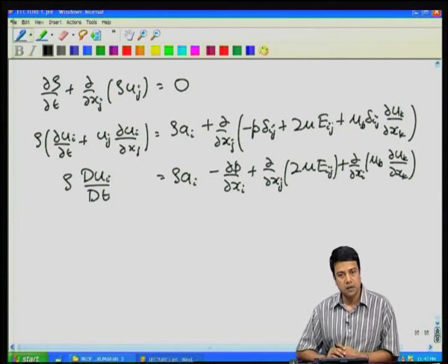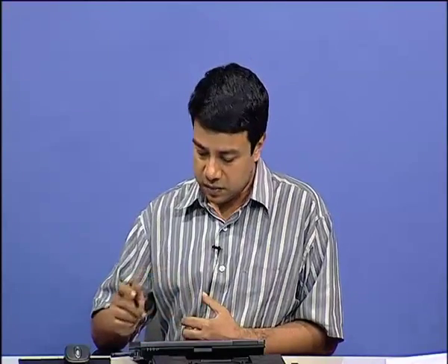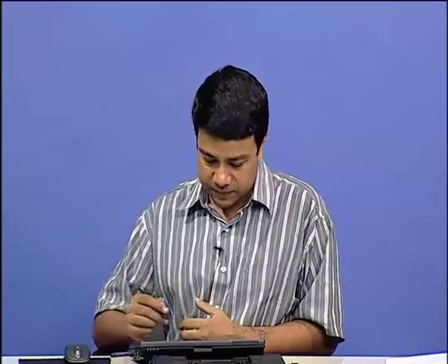Okay. One could of course have more complicated forms of the constitutive relation in the case of non-Newtonian fluids. Okay. In that case, the stress is not necessarily a linear function of the rate of deformation tensor. It could depend in some more complicated way on the rate of deformation tensor. However, no matter how the relations are framed, one has to ensure that they satisfy the frame invariance. Okay. That is, if you translate or rotate coordinate systems, the resulting relationship should not depend upon the specific choice